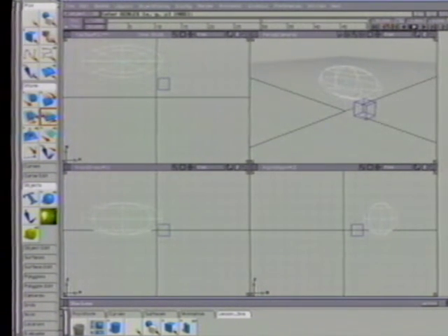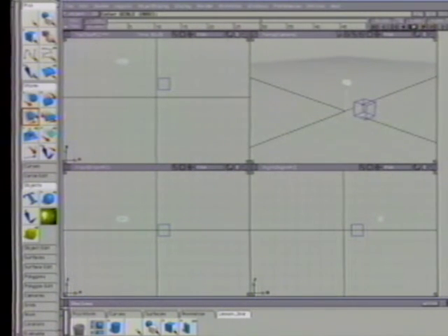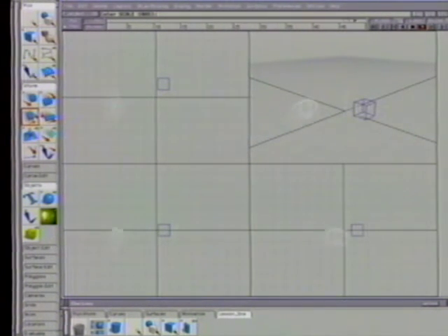You can now see the ball at frame 30. Since this is where you set one of your keyframes, you can see where you set it. X-form scale the sphere very small. From the animation menu, select Set Keyframe. Click OK to overwrite old keyframes. Click the play button. Now the animation is updated with the new settings.